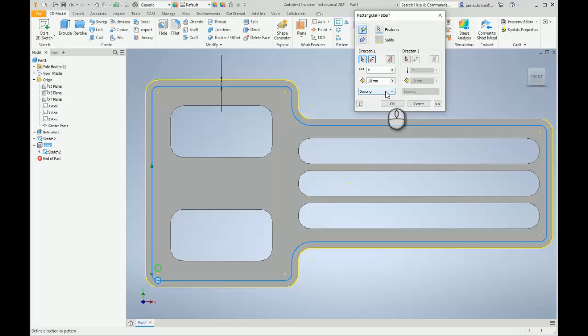Now there's a little bit more I need to do there. So you may or may not have noticed that in the drop down here we have an option for curve length. When I select that curve length, it's telling Inventor that it's using the full length of this curved line geometry, and we're going to pattern, at the moment, this pattern in 2 instances around that curve, and you can see the preview that is generated here for the second instance.